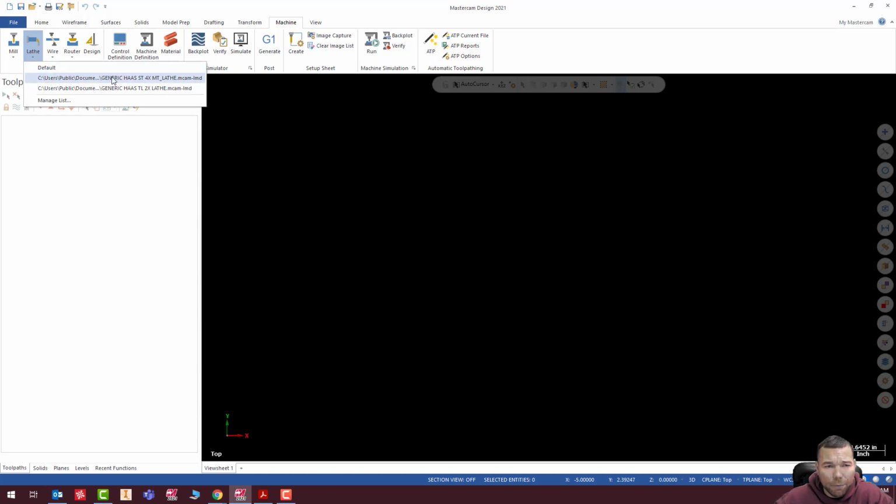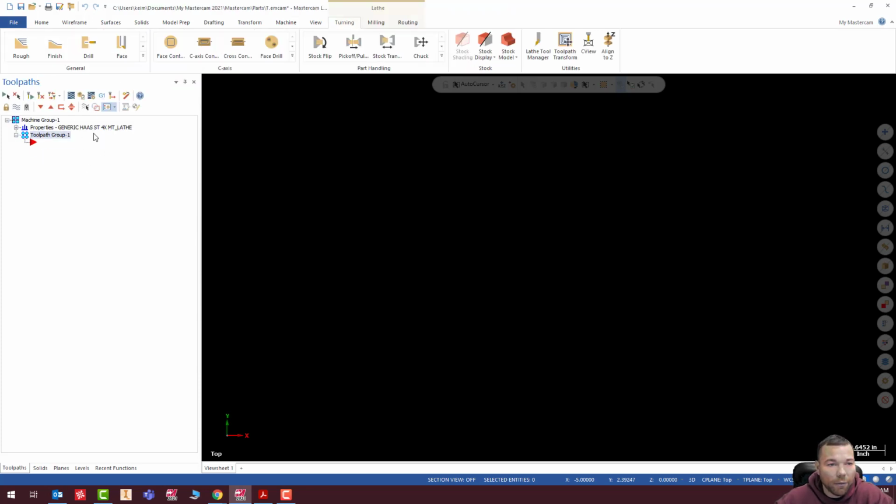You can also pick default if you do not have this post. Hopefully, you have watched the video on how to add posts, and you've added some of these posts to your post processor files. But if you do not, default is fine. I don't grade what post you have selected. As long as you have default, default will work with anything. It'll assume that it has a Y-axis. It'll assume that it has a dual spindle if need be. So it opens up everything. If you pick this 4-axis, this will work fine too. So I'm going to pick this one since it's the machine that we have in the shop.